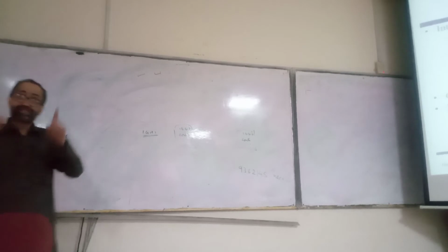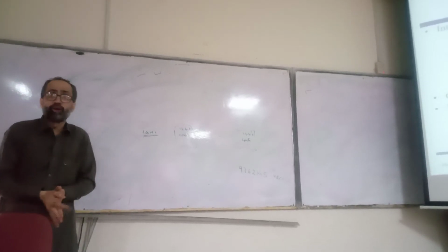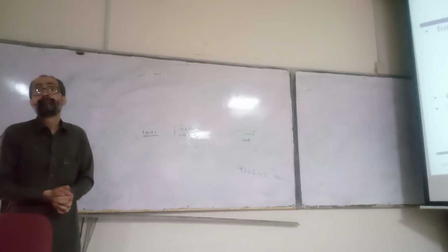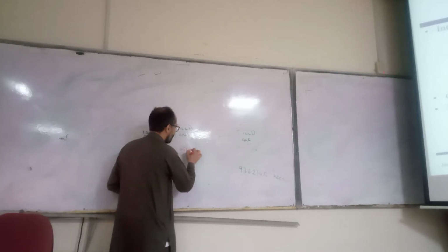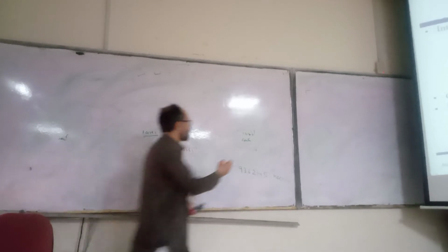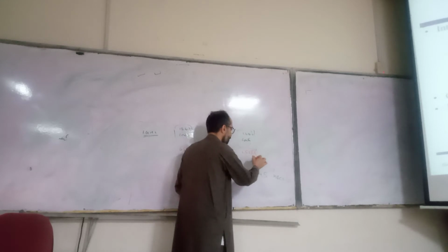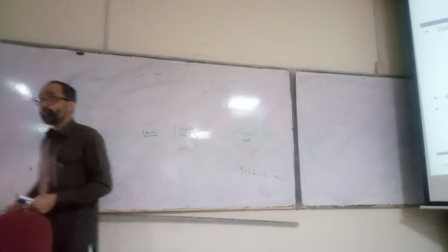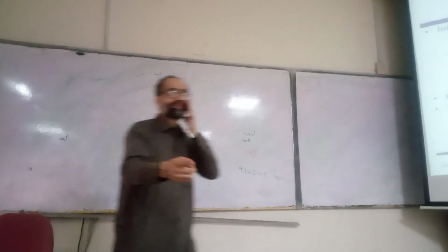Can you model it with a single counter? Why not? Because it's greater than the maximum range. The maximum range of this counter is 65,535. So how can we increase the range? Use the counters in a cascaded fashion.